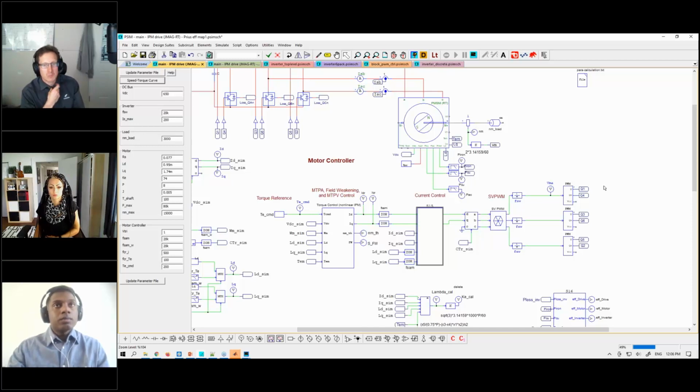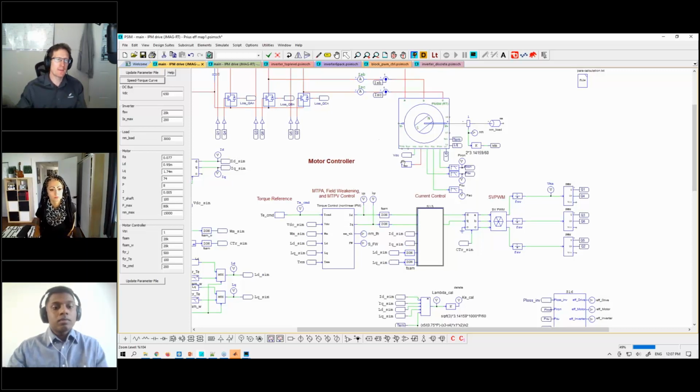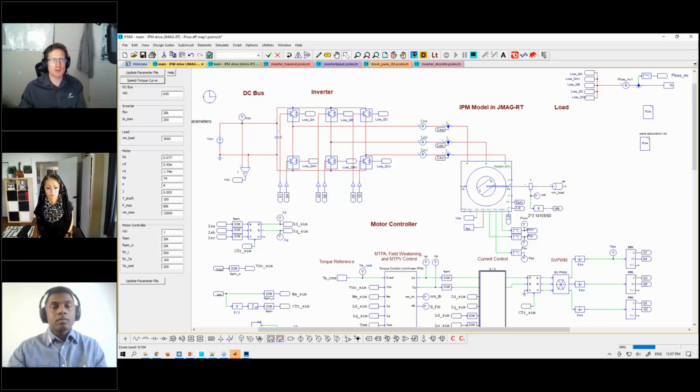There's another question. I'm trying to understand what the question is. It has to do with phase voltages or back EMF. In PSIM, in this simulation, yes, this machine model is generating a back EMF that one can measure if one wanted to. And obviously, the transition into field weakening is driven by the back EMF and the voltage drop across the input impedance. So there shouldn't be any.